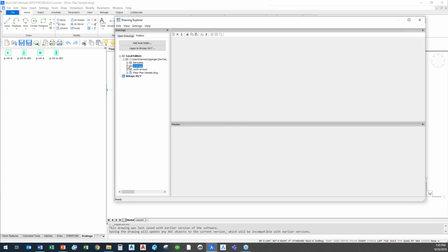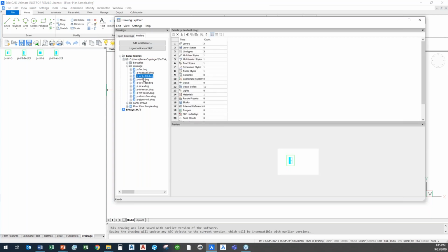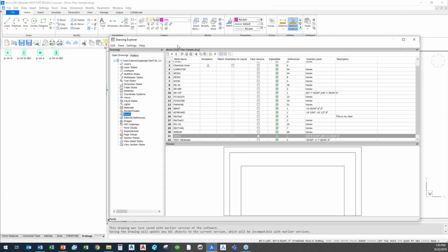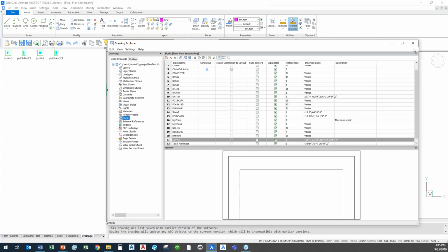And you see I can easily create another tab for bar scales, and bring in all my different bar scale sizes. If I've got a series of north arrows, here are my north arrow drawings. If I've got title blocks and municipal details, I can have thousands of details all in a folder, and I can bring them in. And because these reside out on your network, each one of these is its own independent DWG file, as opposed to what we did before, which was pulling drawings from inside this floor plan that I had open. Okay, so it's just about where you want to store your setups and structures.